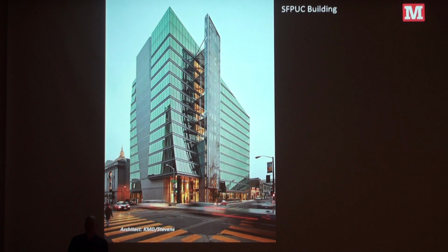That's the design mandate. About 12 years ago, the design was originally base isolated by a very famous engineering firm that Marcy used to work with. And they were able to hit the performance mandate. Base isolation is where you have a slipping plane, so the loads can't get into the building. They couldn't afford it. So about 7 years ago, they used another system, which was a steel-bolted moment frame with hydraulic shock absorbers between it. When it would displace, the shock absorbers would convert motion to heat. And that project went forward.